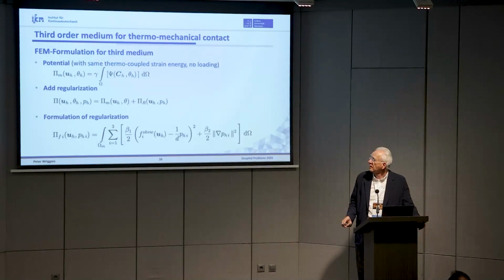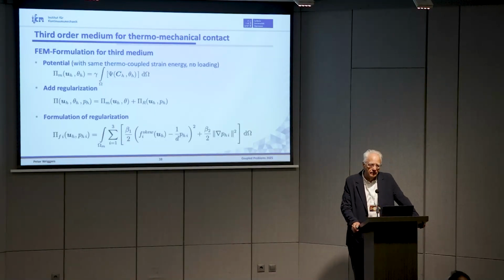And what I have done in this code is not to use a staggered scheme, but to solve the full scheme, the full matrix, which means that I have to solve a non-symmetric equation system. But you can also use a staggered system for the temperature, because in the nonlinear case, the heat flux depends on the deformation, and on the other hand, the constitutive equation for the stress also depends on the deformation.